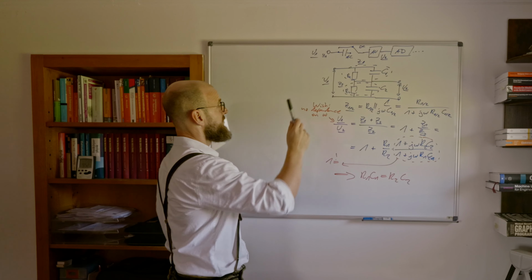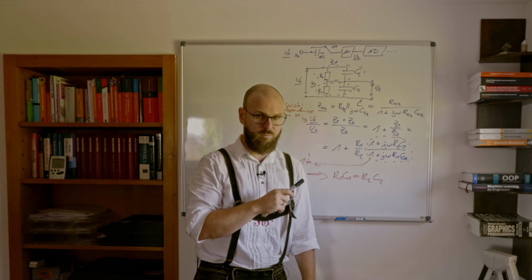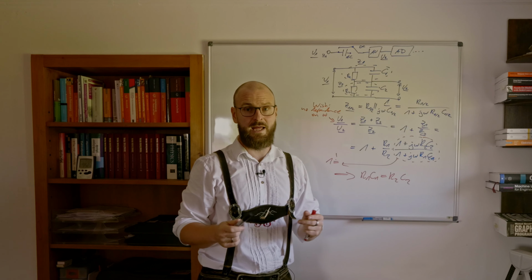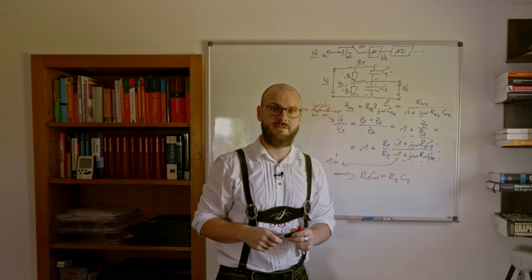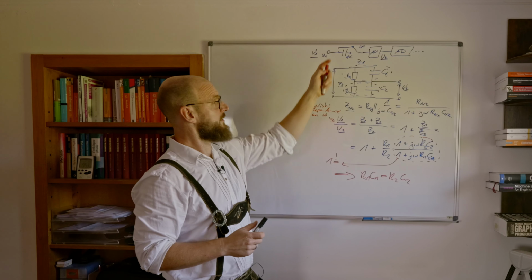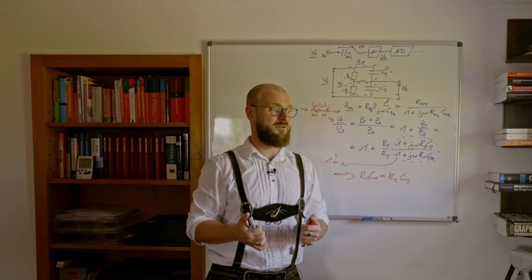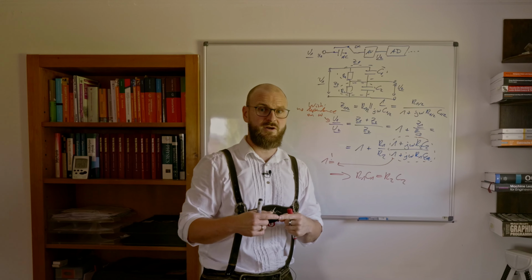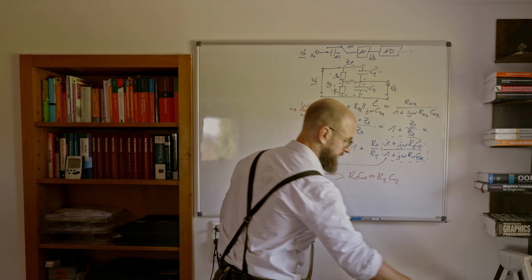And now imagine we do the same stuff using our oscilloscope, for example, placing your power plug next to your measuring wire. What will happen? Your power plug will have some radio signals with around 50 Hertz, which will be received by your wire connected to your oscilloscope carrying your measurement signal. That's bad. So you get a mixture of a 50 Hertz signal and your measuring signal. That's something you don't want.